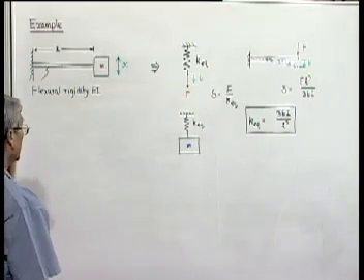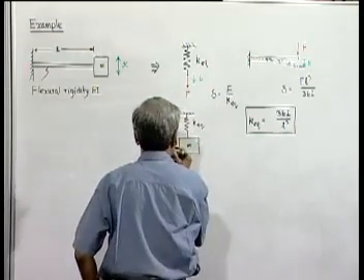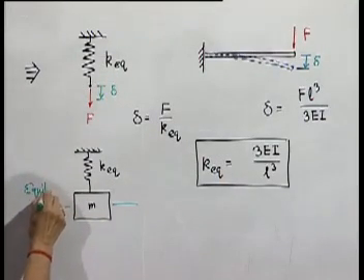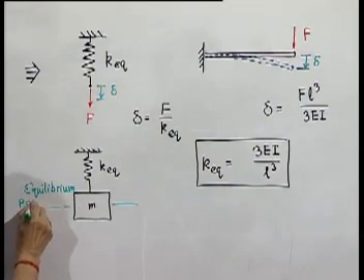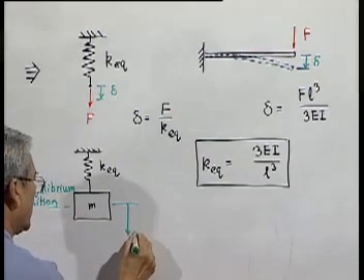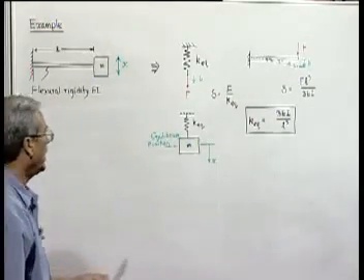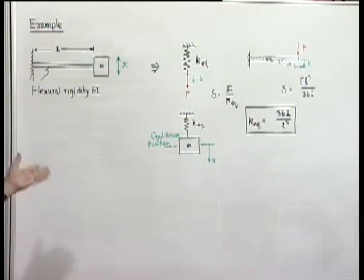Now we have seen the equation of motion. This is the equilibrium position, and we measure x from here. We should remember our previous analysis and recognize the fact that we do not have to consider gravity anymore, because we are measuring the displacement from the equilibrium which was under the action of gravity.